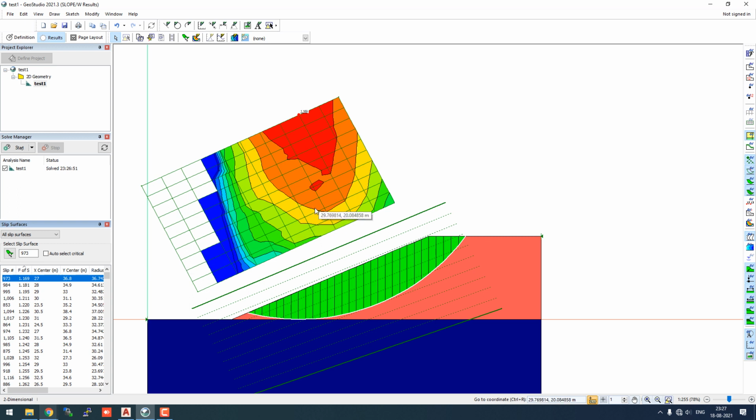So you can see the effect of water, pore water pressure, and these parameters can affect the soil properties a lot. So whatever we are considering in any geotechnical situation or any geological situation affects the whole factor of safety a lot. So you have to be considerate of that in that case.